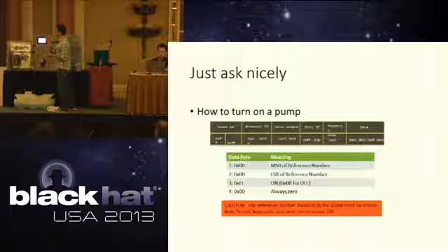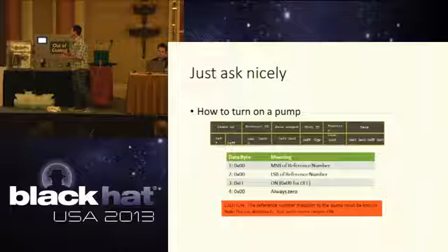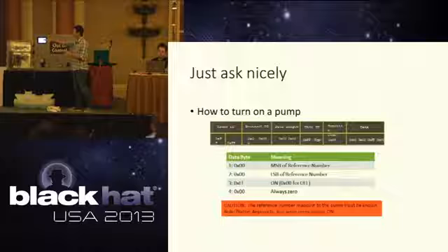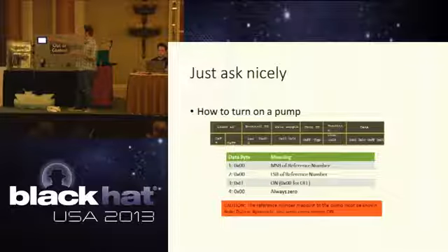So our data is that table down there. We have the most significant byte of our reference number, the least significant byte of our reference number, and I'll tell you in a second what our reference number is, and whether or not we want it to be on or off. FF is on, 00 is off, and the last one is just always 0.